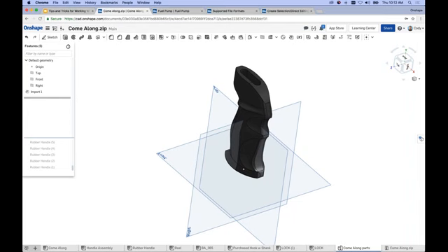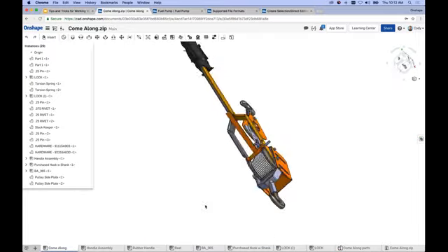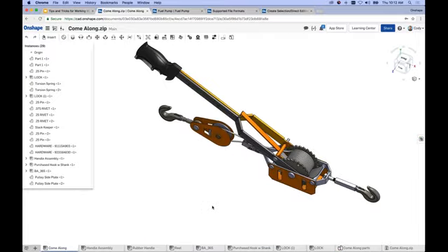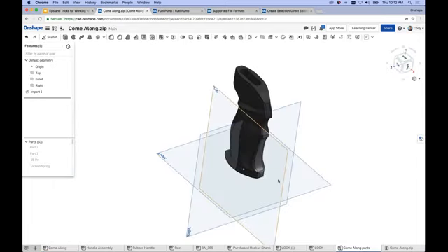Question. Why can't this part studio come in correctly like it does when I import all into a part studio? The assembly will come in the correct position. All the parts are correctly oriented in the assembly. In this case, I'm importing in the assembly. But when you import and translate, it's taking all of the parts and putting them into the same position, the position they were originally modeled.